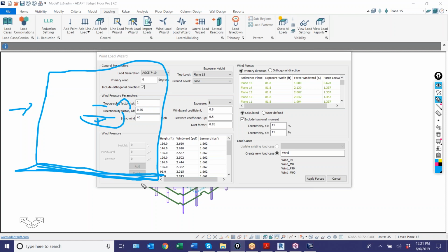The program cannot actually apply a rotational drilling moment around the z-axis. So in order to simulate this, we actually produce a couple. We produce a line load in one direction. So if we take a resultant, this is our, let's say, X positive, and this is our X negative. And that produces a rotational moment for the slab and for the entire system.